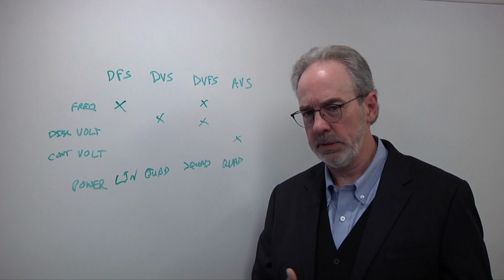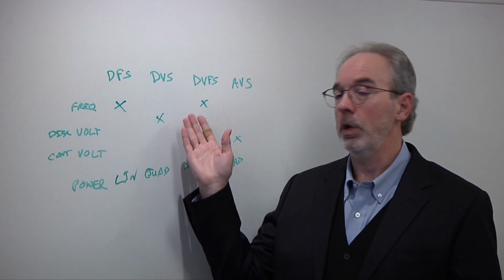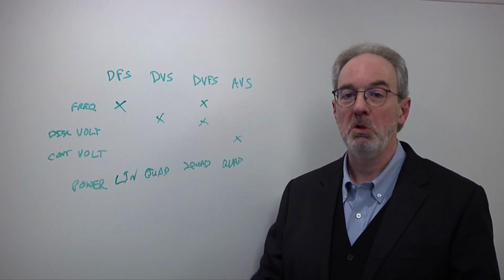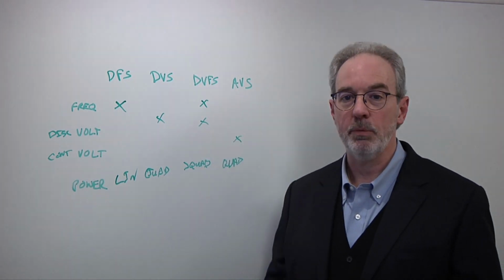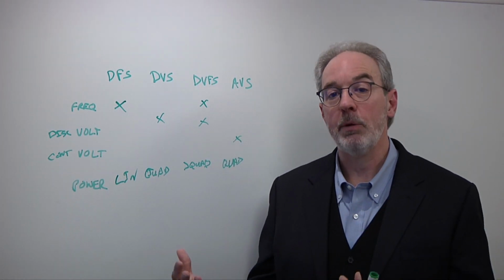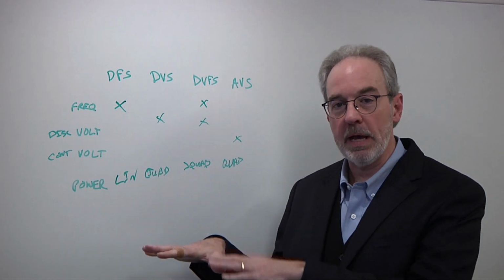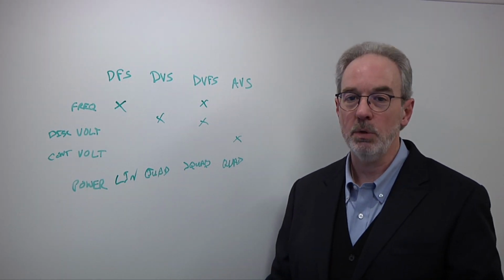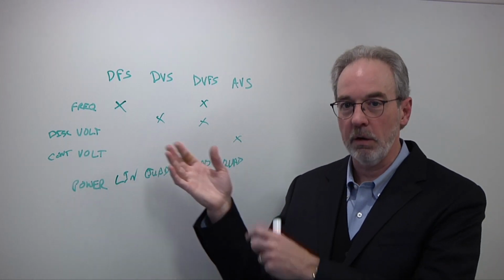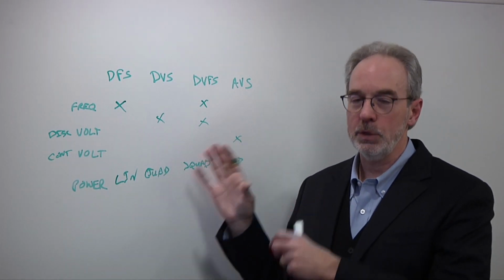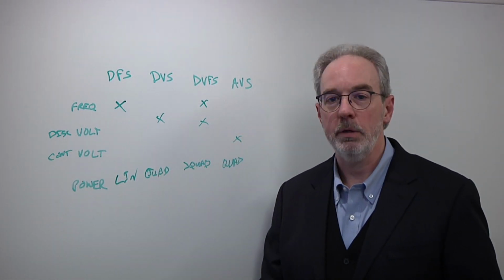Throttling is something that's existed in phones and laptops for a long time, where you run the voltage and the frequency as high as possible, then you run into some thermal limits and you have to be able to manipulate that. That's how you get the maximum performance level. The way you get the maximum battery life is that you turn everything down to as quiescent a state as possible to save power. That dynamic manipulation across frequency, which is linear, and voltage, which is quadratic, is where you get these savings, and that's what people are starting to deploy.